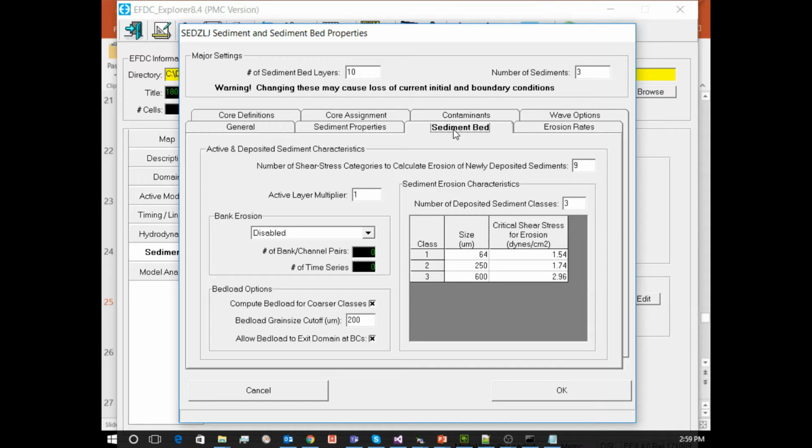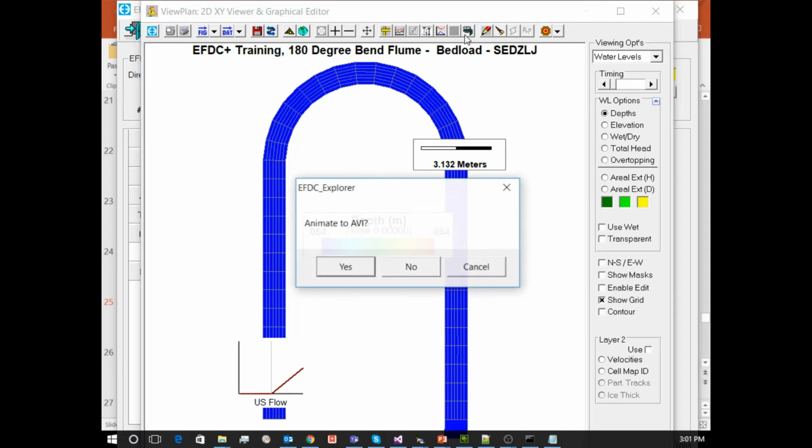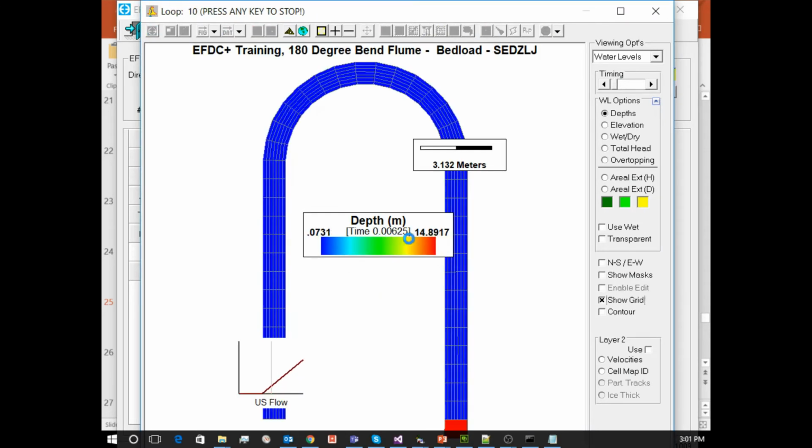So now you have a lower bottom elevation, the same water that you had essentially, assuming that things are not changing that rapidly anyway, so the depths are the same. Then it resolves the pressure solution, and as the bed drops down, water will move in to fill that void. So you have a nice smooth pressure solution. If I wanted to animate water level every single time step, you'll notice that your maximum depth, because it's all flowing off into this tank that's 1 meter square, and it's just filling up, ends up with like 600 or 700 meters of water in my theoretical catch basin.